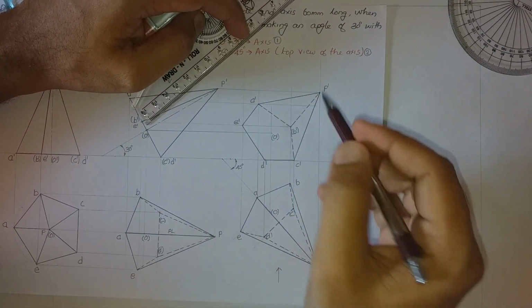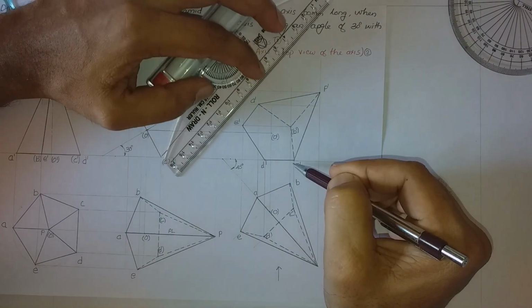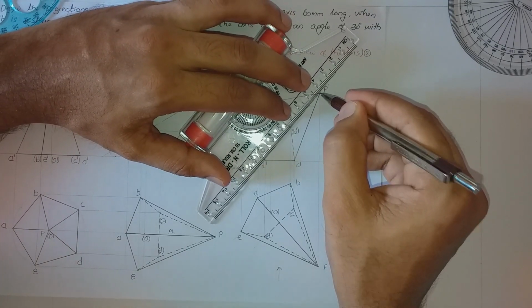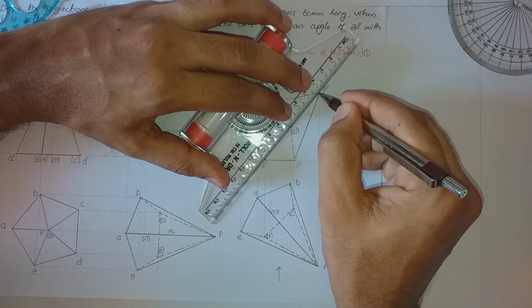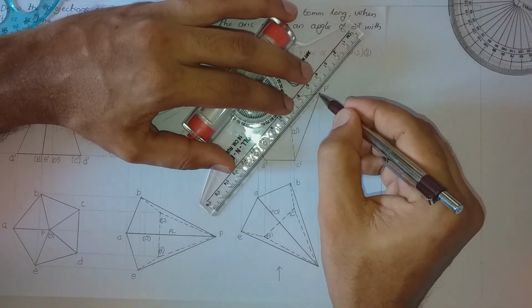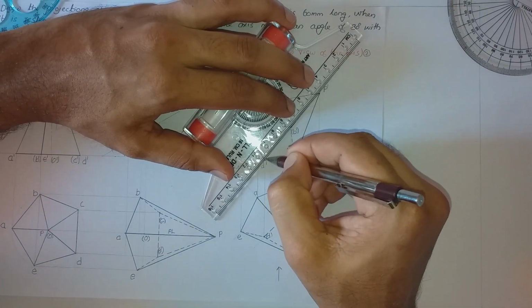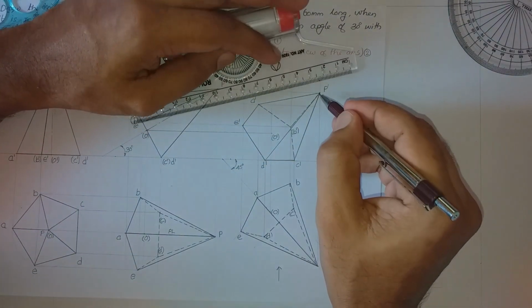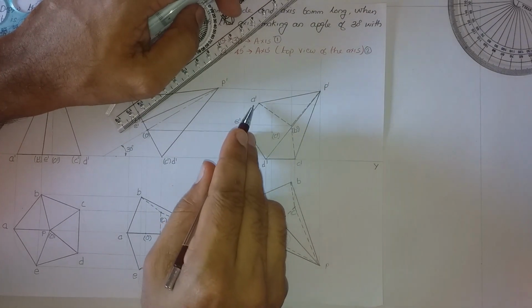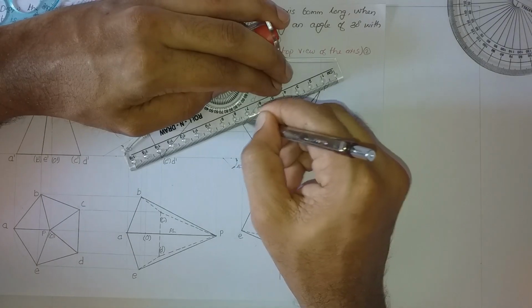Now we shall draw these slanting edges. PA is already here, PB is here, PC is already here. So PD is yet to be drawn. So what about the visibility of PD? PD is actually crossing a confirmed hidden line, which is BC. So definitely PD will be visible. Next is PE. When you are drawing PE also, it is crossing a confirmed hidden line, which is AB. So definitely this edge also will be visible.